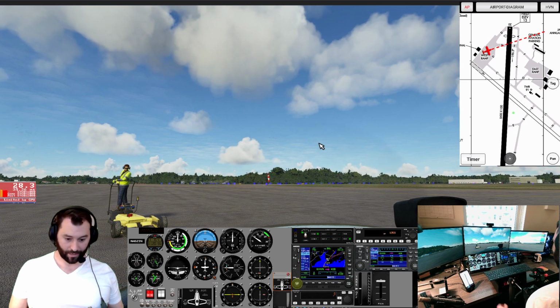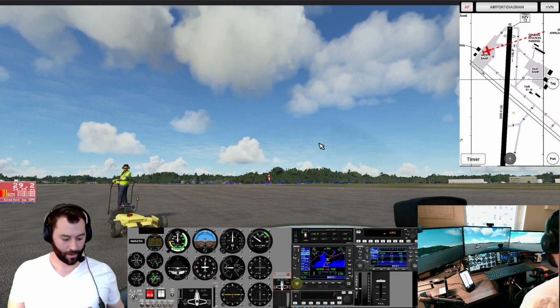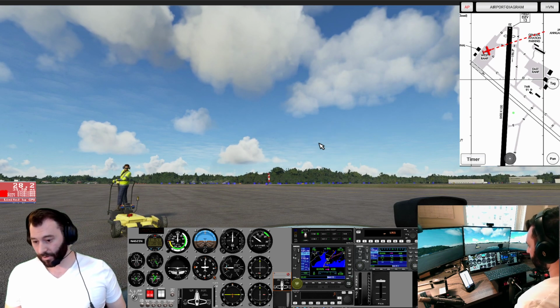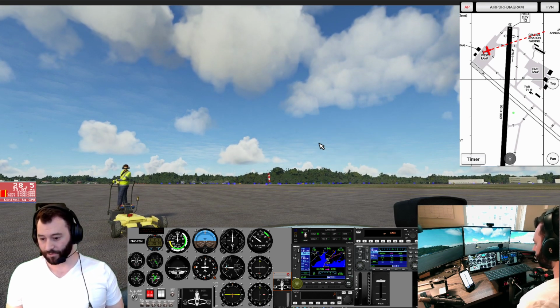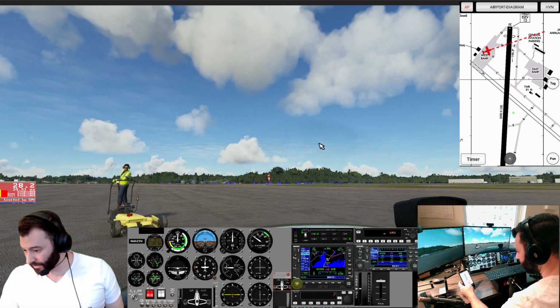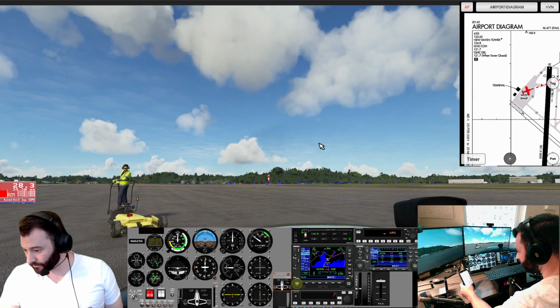So we're running here. I think we have the brakes set. We do. We're not going anywhere. We've got 1,000 RPM. We're looking good there. We'll look at our pressures, temperatures. We're all in the green. Vacuum pressure, amps look good. So steady state there. Let's check ATIS.